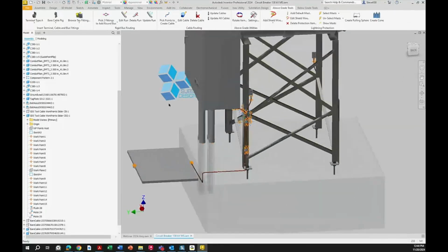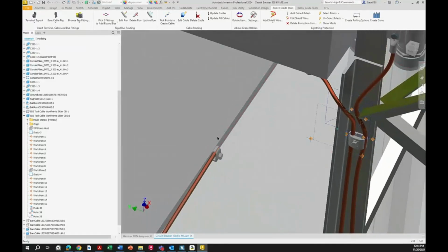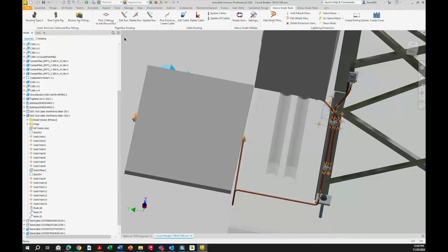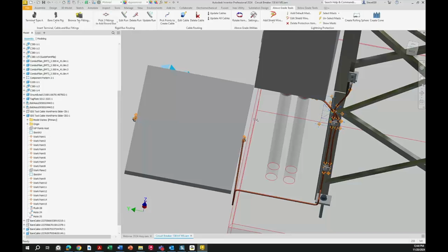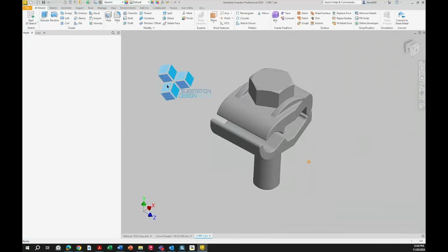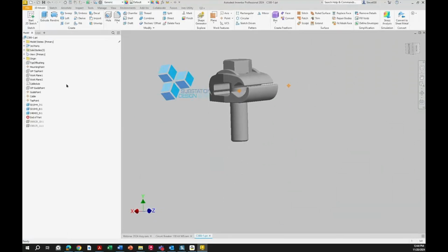That model state issue here, I worked with it down here. So when I'm connecting down here to that fitting, if I come in here and change my selection, so this is my fitting again. It's a similar fitting. Well, we talked about this before, but now I'm using that model states here to flip, just like what we did. But what also is in here is guide point, tap point, cable. So now I can use it as a tap point as a ground lead.